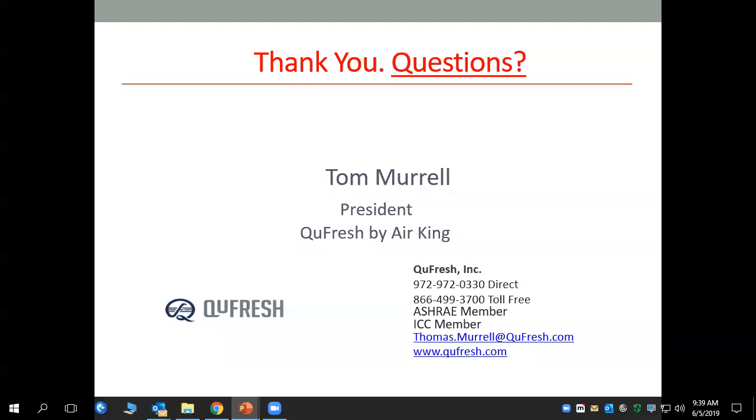So I think literally for under $200 more, or a couple $100 more, having the only way to ventilate a home in Texas, in my opinion, is with some sort of smart strategy. When that outdoor air is too hot and too humid, you don't want to be bringing it in. And so having that controller and that sensor, and then that fan that's only pulling a fraction of the watts, ducting that separately, or not ducting it separately, but the same setup that most builders are using now, but just having, whether it's QFresh or one of your competitors, my main point being, it has to be some sort of smart ventilation.